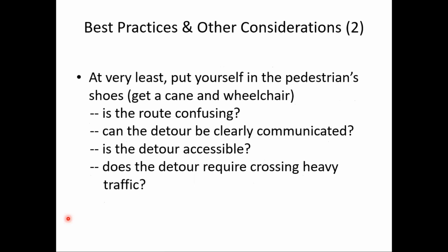Or I like to say, at the very least, put yourself in the pedestrian's shoes. Get a cane and a wheelchair and go through the route. Is it confusing? Is the detour clearly communicated? Is it accessible to someone in a wheelchair? Does it require crossing heavy traffic? This can go a long way. Also document this, and this is a great way of showing you're making a good faith effort to address the accessibility issues.